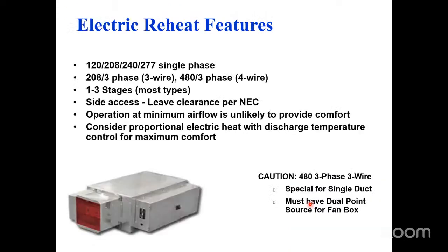You can also do electric heat. With an electric heater, you have several different options. You could pick the voltage that you have, right? Usually it's going to be 3-phase because there's a lot of heat involved in all these boxes when you start adding them up. So you're picking 208 or 480. You can do single phase. That is rare, but you can ask for that. Or maybe you got one little tiny small zone. It doesn't really need a big heater. You can get 120 volt single phase or whatever there. You can do that if you want to. So all of those voltages are available, every possible scenario.